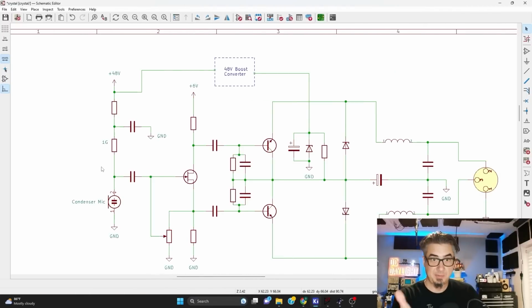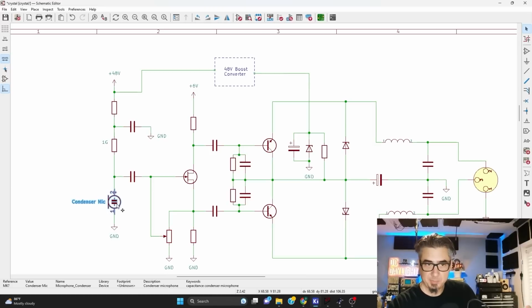So before we look at this, let's just take a quick glance at the schematic. So here's the schematic as best as I could reverse engineer it. I understand that this circuit is called the Schoeps circuit. So it takes a single-ended signal and turns it into a differential signal to send over a long cable run, right? So we have our actual condenser here, that's our capacitor, and we need to provide a relatively high voltage on those two plates of the capacitor in order to be able to measure or take that analog signal and further amplify it.